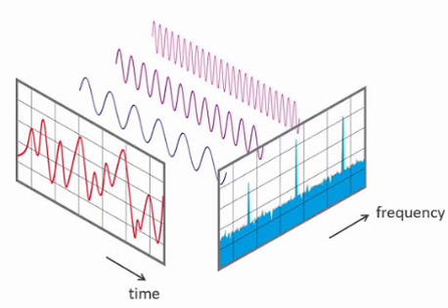A digital filter is a system that performs mathematical operations on a sampled discrete time signal to reduce or enhance certain parameters of the signal. There are two types. First, the finite impulse response filter, where the impulse response is of finite duration. The difference equation is given by y[n] equals sigma i equals 0 to N b_i x[n − i], where x[n] and y[n] are input and output respectively, N is the filter order, and b_i is the value of the impulse response at the ith instant.